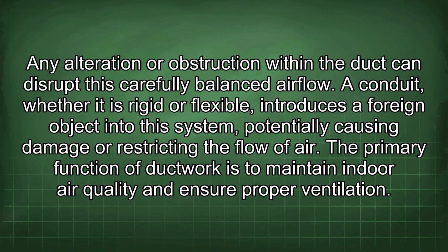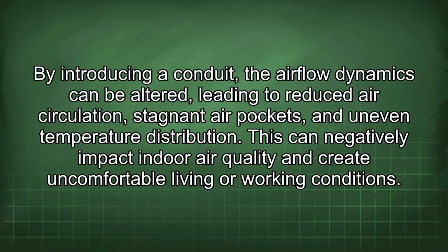A conduit, whether it is rigid or flexible, introduces a foreign object into this system, potentially causing damage or restricting the flow of air. The primary function of ductwork is to maintain indoor air quality and ensure proper ventilation. By introducing a conduit, the airflow dynamics can be altered, leading to reduced air circulation, stagnant air pockets, and uneven temperature distribution. This can negatively impact indoor air quality and create uncomfortable living or working conditions.